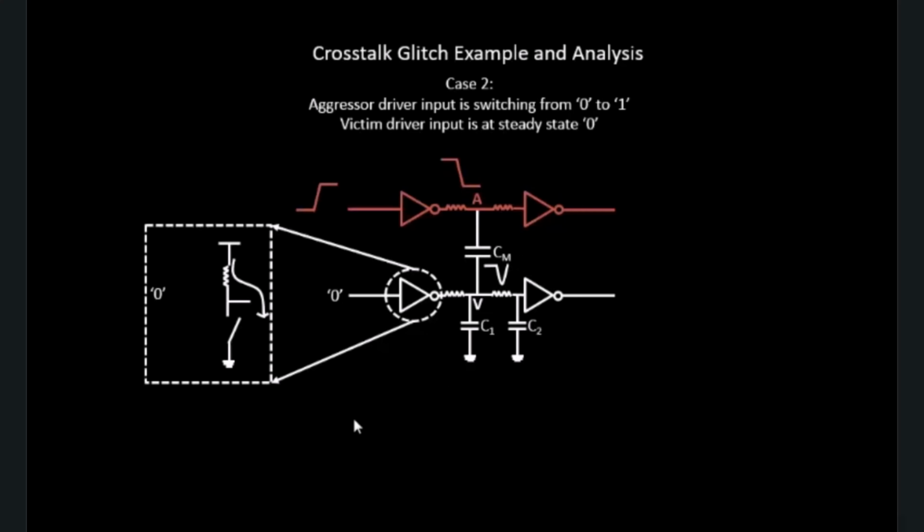Okay, so that is what has been the observation in the past. So let's assume that the on resistance is very low. If the on resistance is very low, then this particular VDD will be continuously supplying the charge, and will make sure that this particular capacitor again retains its logic 1 voltage.